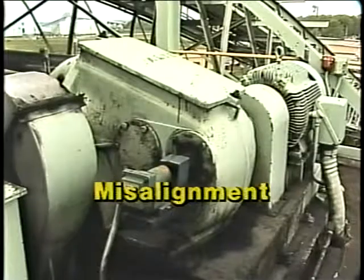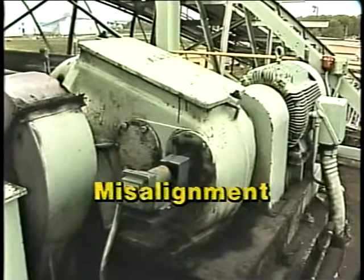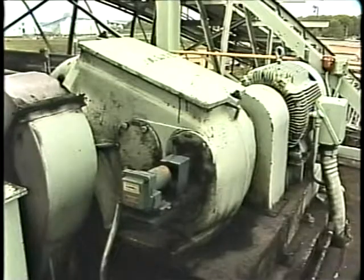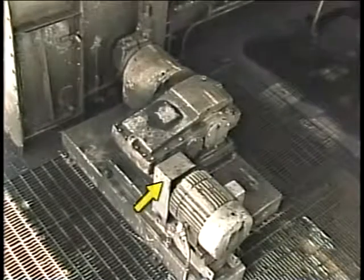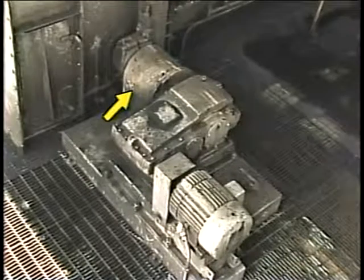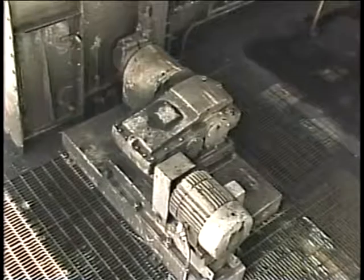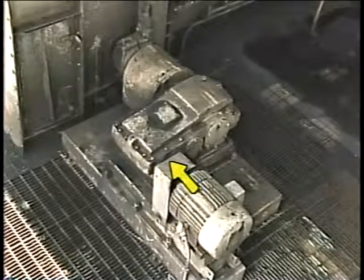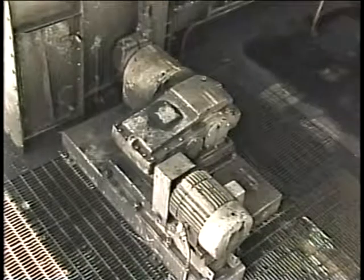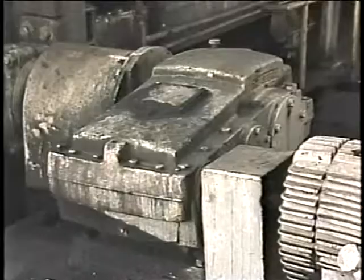A gear unit being out of alignment or position is another common cause of bearing failure because it places an additional load on the bearings. The malfunction of either the couplings between the gearbox and the prime mover or those between the gearbox and the driven equipment could be the cause of bearing failure. A failed coupling could cause excessive vibration to be transmitted to the gearbox and bearings. A failed coupling could also throw a gearbox shaft out of alignment.